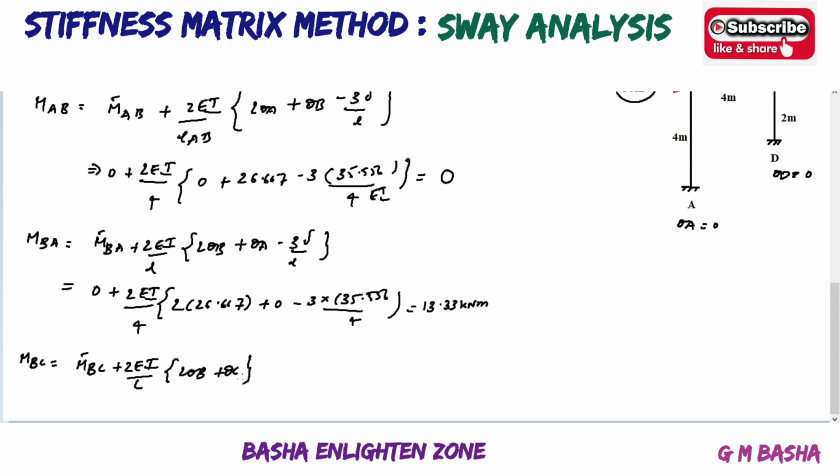Sway only leads to that particular column. While solving slope deflection equations, we also apply the delta value only for the columns, not for the beam portion. In the same way here, whenever sinking is given, you can apply that sinking value only to the columns, that is AB, BA, CD and DC, not for BC. So you can remember this as a note point.